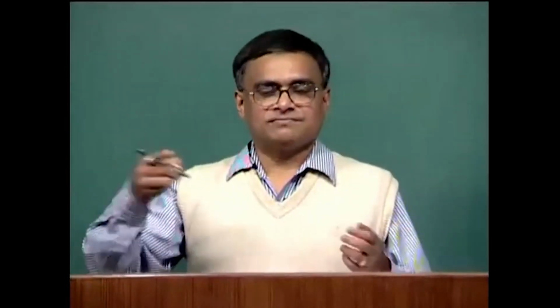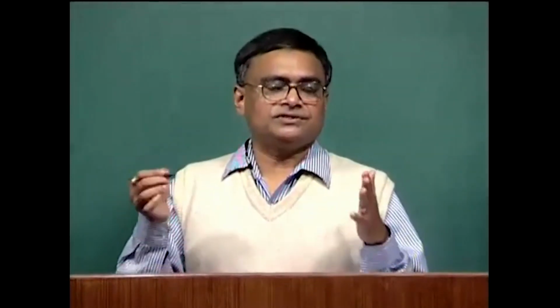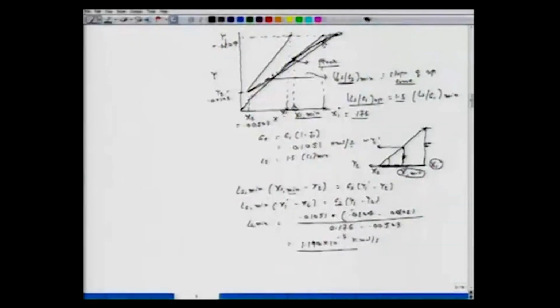We have the equilibrium curve which is given to us. We know the operating line. Wherever there is a pinch, y will be equal to x, and that point will satisfy both the operating line and the equilibrium curve. So one can obtain x1 min from there also. From that, then go back and put back the equations to obtain Ls min. But if you have a graph and you do a nice job, then there is no need to solve analytically. So now we know Ls min.